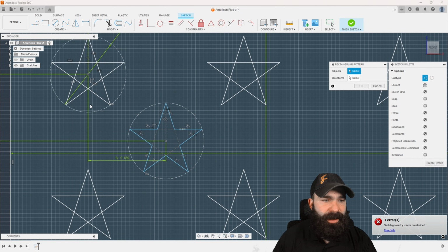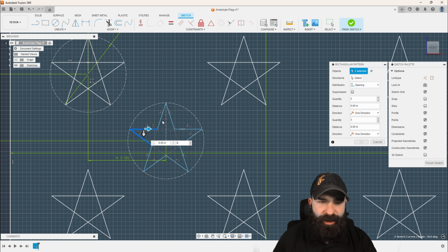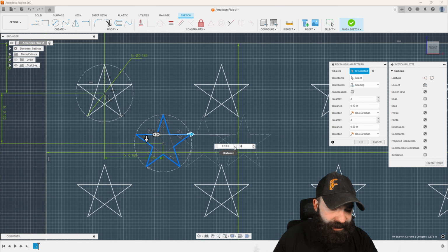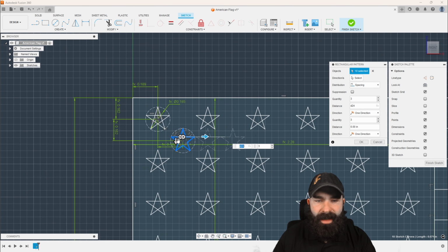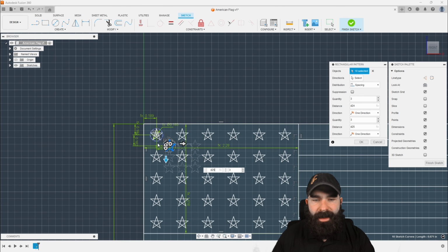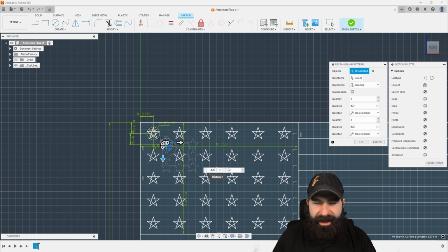I'm going to go ahead and say rectangular pattern. I'm going to pick the actual pieces that I want to pattern. And as you remember, in the case of what I'm doing, we actually have dimension D4 going this way, or D24 this way. And, oh, I typed that into the wrong area. We're going to go ahead and start with 3 of those, and we're going to put D24 here. And then going down, I know that's D25. And again, we want to do everything times 2.